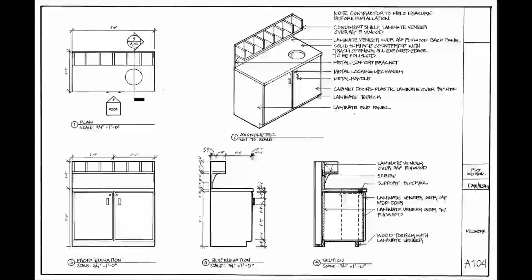But notice here on the dimensions, there are parts of the dimensions where I could fit my dimension perfectly, and it floats just above in my consistent text size, and it works great. But there's other places where it just won't fit. So you can see here pulled out, it's kind of a leader, but it's an arc-shaped leader. And I pulled that dimension out just to the right or left, depending on where it fits best, and wrote it as clearly and neatly as possible, because again, I'm trying to avoid the overlap with the tick marks.